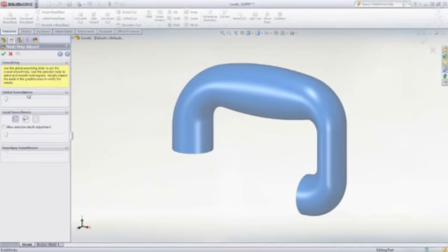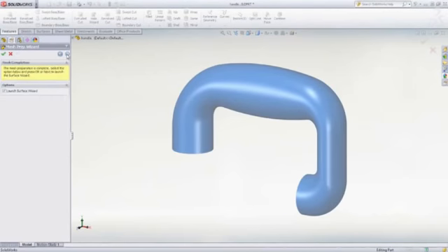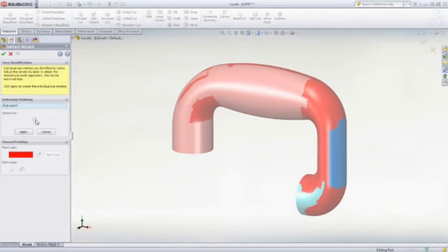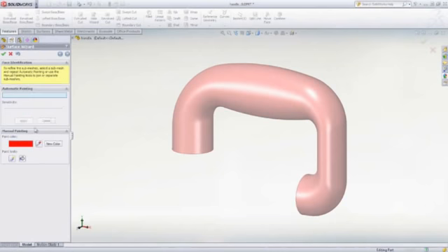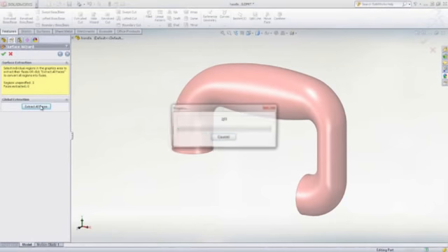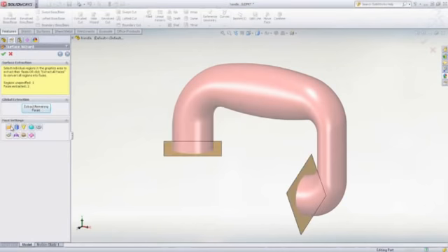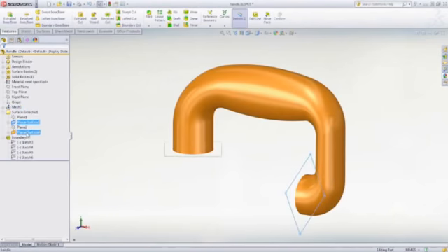And finally, the model can be smoothed to help rectify jagged or unrefined areas. Once the mesh is created, you can use the Surface Wizard in automatic or guided mode to map surfaces to the mesh. Using standard SolidWorks surfacing tools, you can then trim these surfaces to form a 3D solid model ready for manipulation or use in your design.